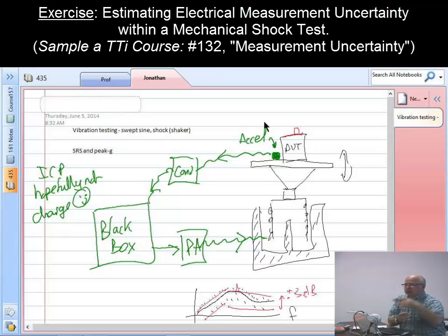was like a cube. Take the lid off, put the components inside, seal it back up again was the fixture. And they had a little resonance right on that frequency. And so this badly designed fixture was causing the sweep to abort all the time.